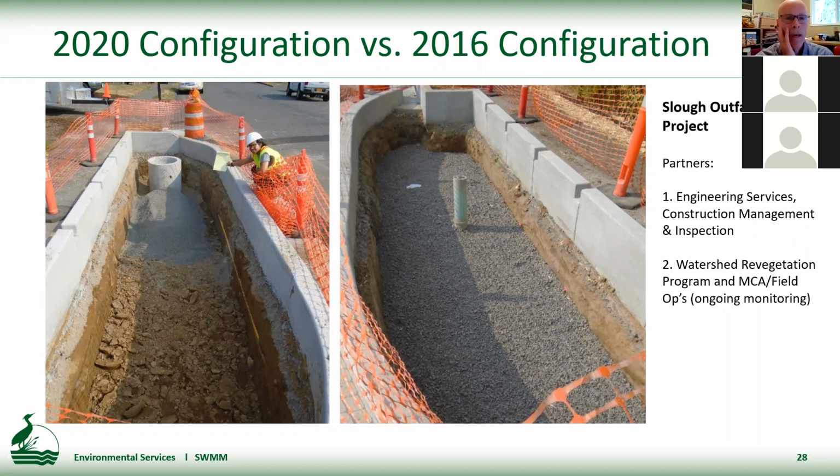So the photo on the left is of the new underdrain system. You can see it's an infiltration system, right? There's no liner there, but it's got that shortened underdrain and the mounded gravel overlaying the shortened underdrain with a flat top. Again, this angular material allows for that, and the beehive standpipe at the end. And then on the right, that's the thing we've been building for many years, which has a rock gallery that extends the full length and breadth of the facility. You're looking at the surface of the choker or filter layer there. Next.